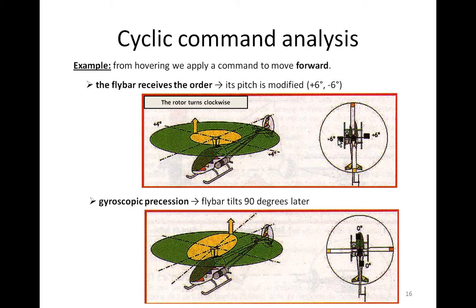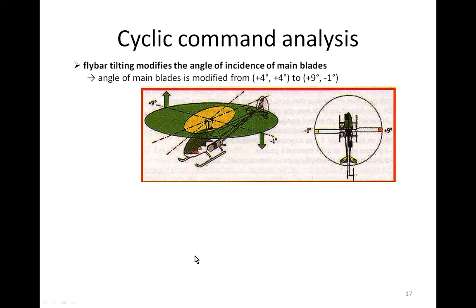The flybar turns clockwise, so the force here will apply 90 degrees later, so here. Then the flybar will tilt forward. When the flybar tilts, the main blade pitch changes.